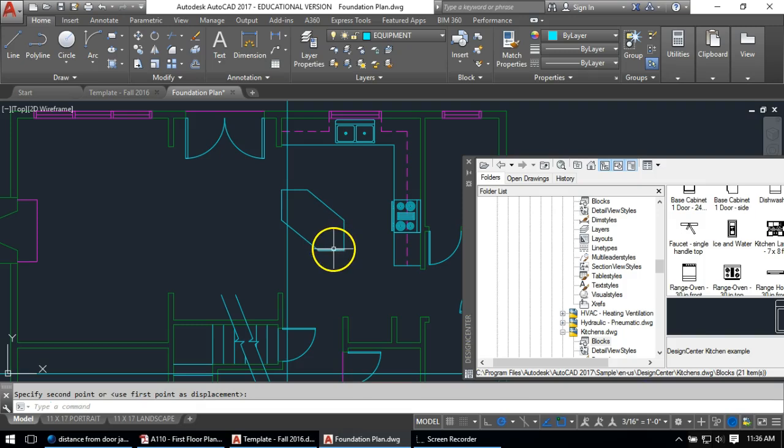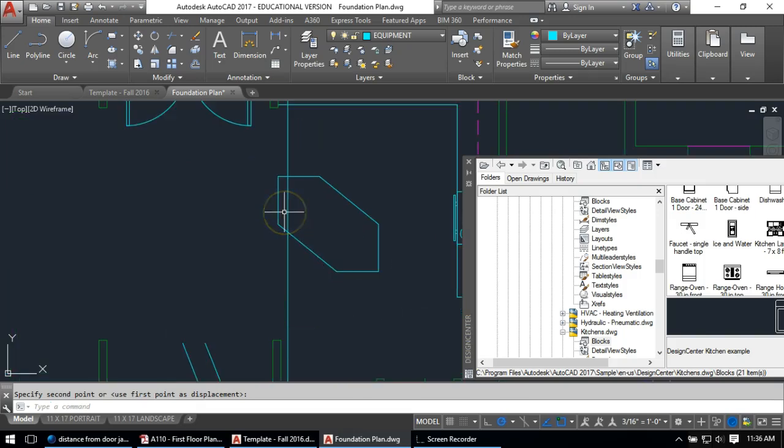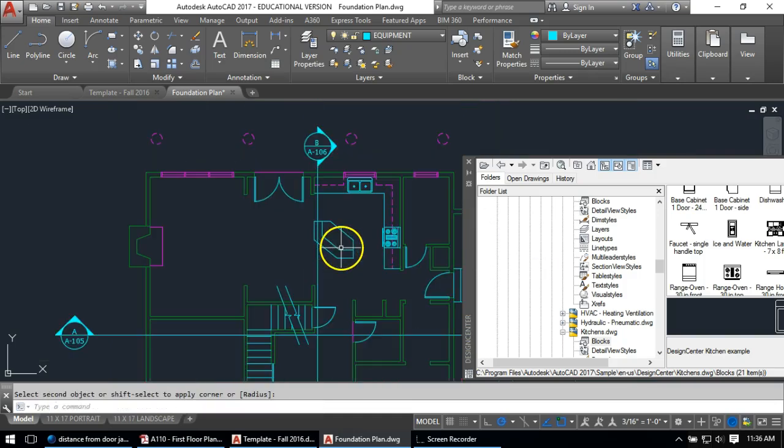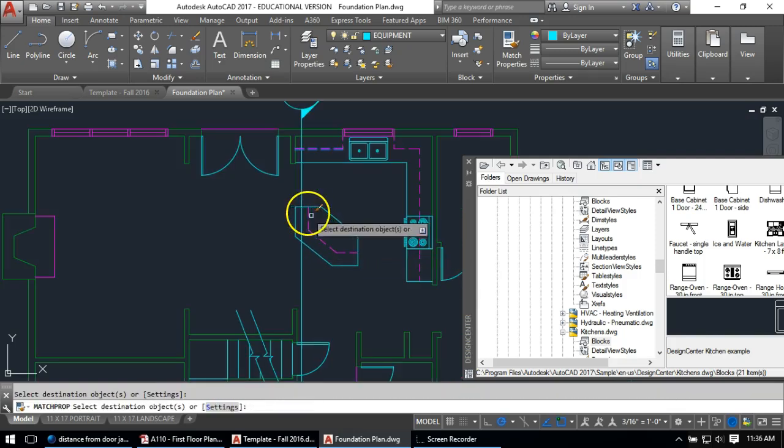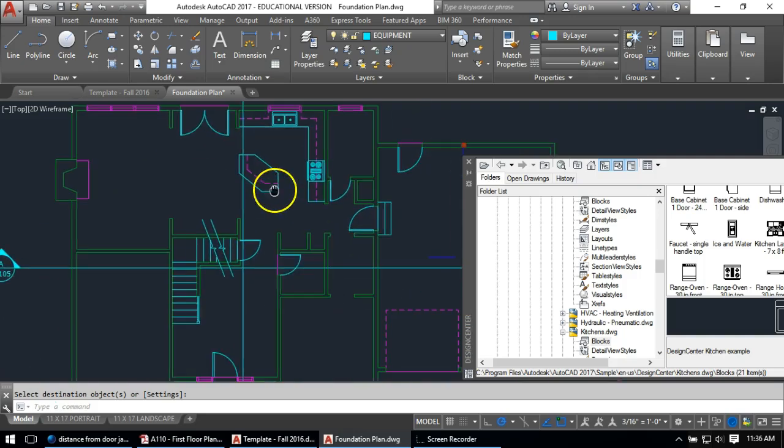Then we got some inside lines. I don't know what the island actually has in it, because that dotted line could be a few things, but it's clearly a foot offset from the back. So I'll offset a foot from the back, fill it, fill it, fill it, and put those on the hidden layer. Just like that. Got that dotted line there.